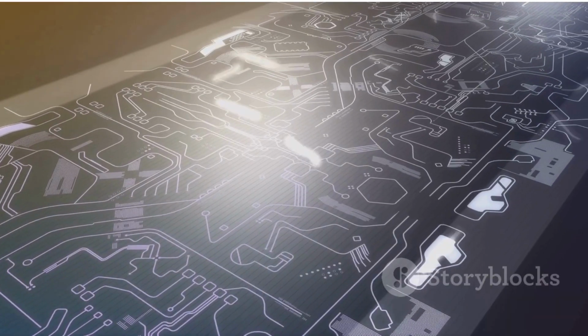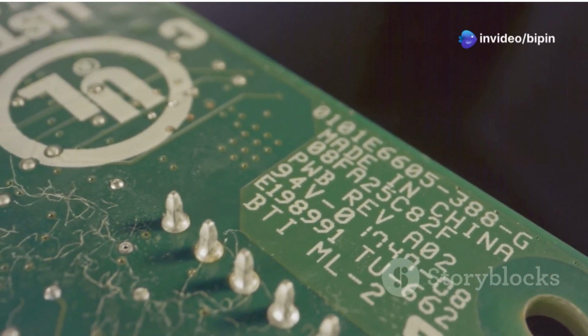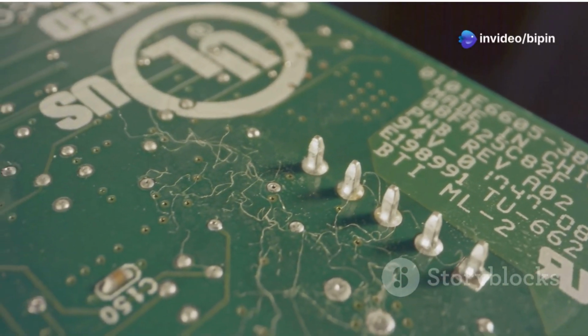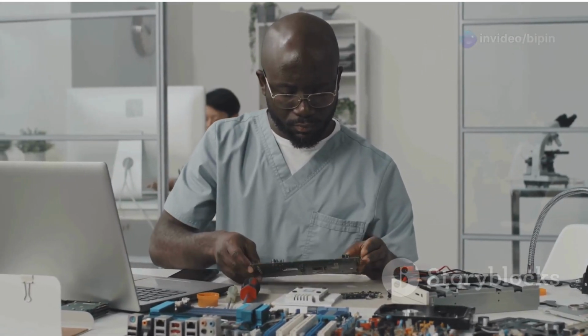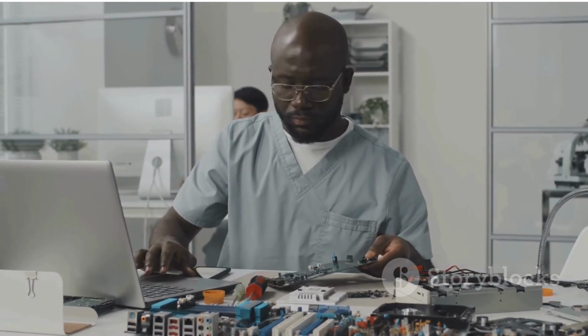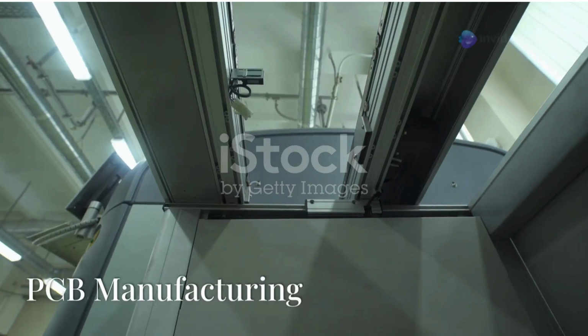This includes things like traces that are too close together, components that are too close to the edge of the board, and incorrect trace widths. Carefully review any errors or warnings flagged by the DRC and make the necessary corrections to your design. This step helps ensure that your circuit board will function as intended.